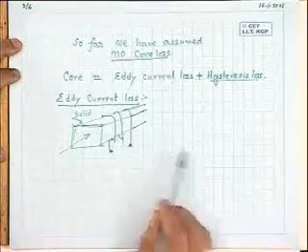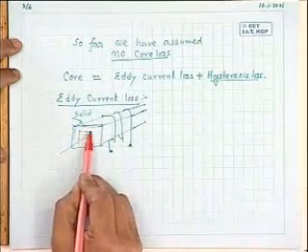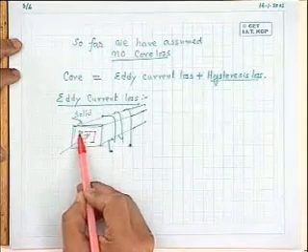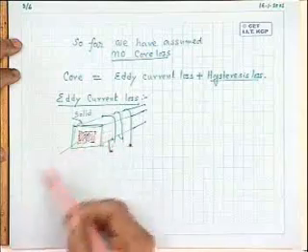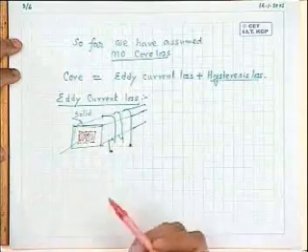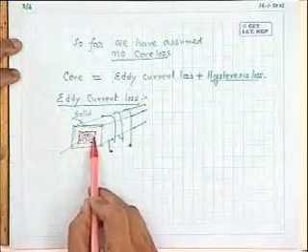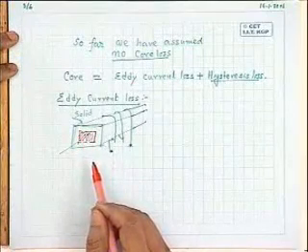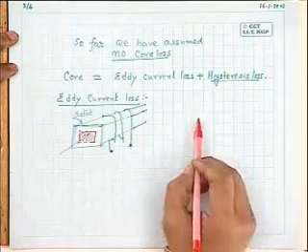Now if in this core of this material you consider any closed path, through this area there is a change of flux density. Okay. So in this closed path there will be induced voltage, as there is induced voltage on a single turn of a coil.